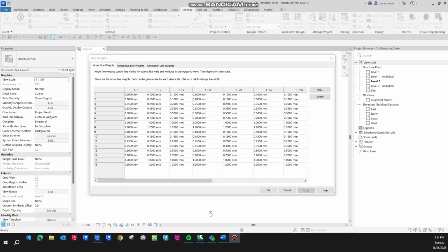Right, so we've copied all the line thicknesses to the various scales that I want. Like I said, I use the first number 1 to 8 for drafting or for presentation, and the rest would be used for modeling. So this is when you drop your actual 3D models onto a sheet. I use that as well.